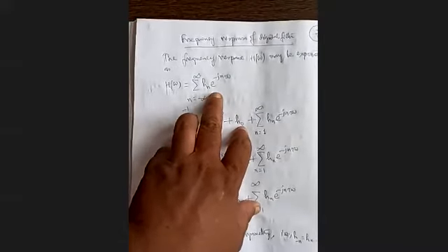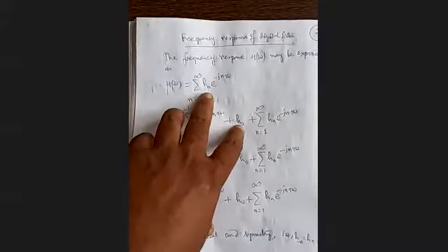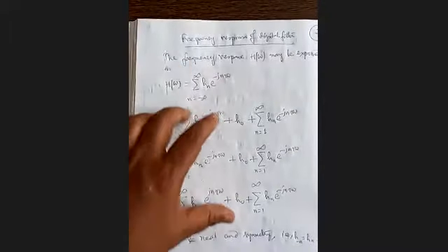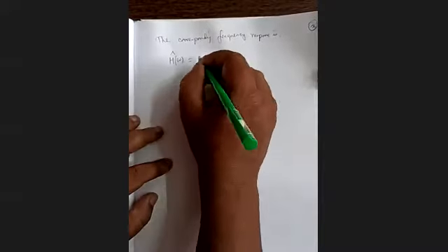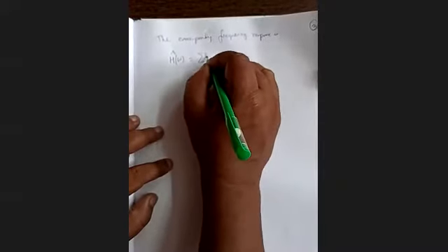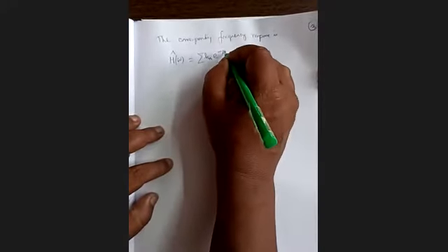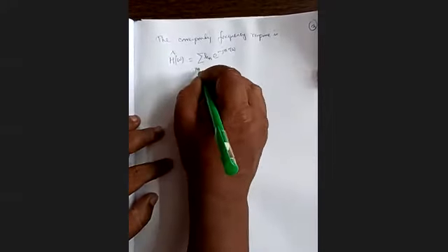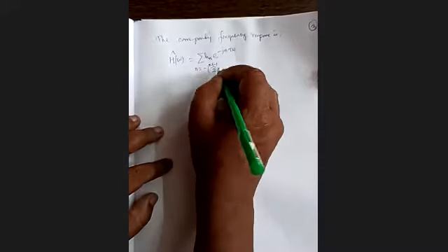So here also it will be the same thing. It will be h cap, and h_n cap, but it will be up to a finite number of terms. So once we get that estimate, we can get here also a frequency response H cap omega equal to the summation of h_n e to the power minus j n tau omega, where n is varying from minus (m minus 1)/2 to plus (m minus 1)/2.